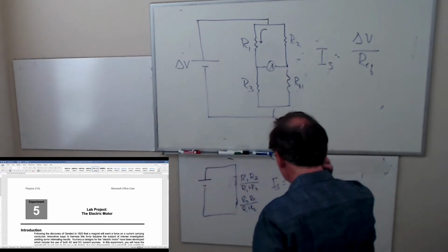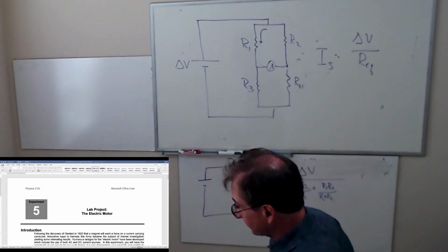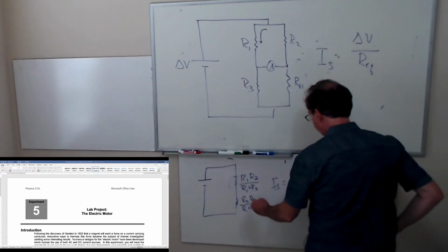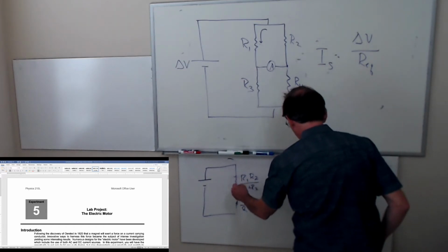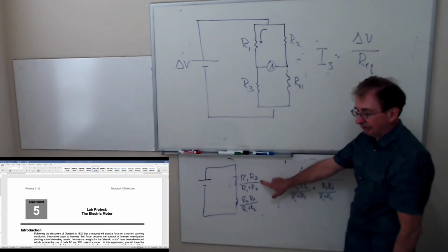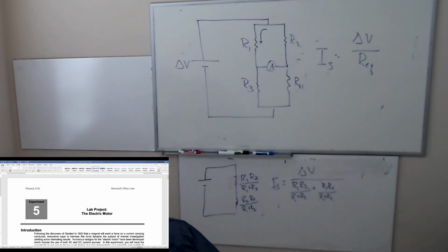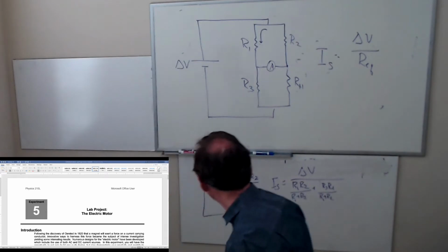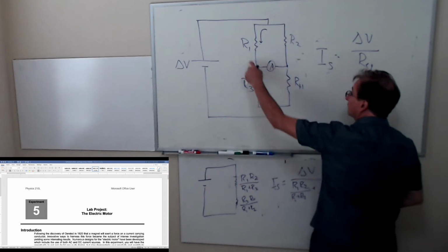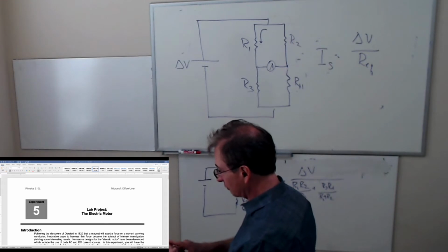Okay. So, you agree this is the total current in the circuit? So then the voltage across this guy is going to be this times that, right? Hold on, let me move the chat box so that I can see the whole chat box. So this times this is the voltage across this guy. Then I take that mess and divide by R1. That's it. So isn't it true that I got it in terms of R1, R2, R3, R4, and the power supply voltage?